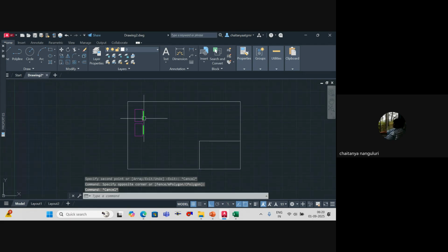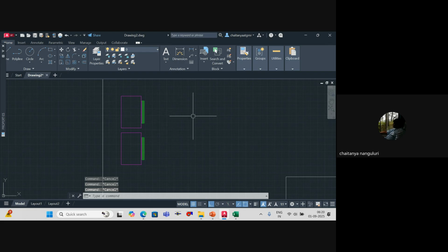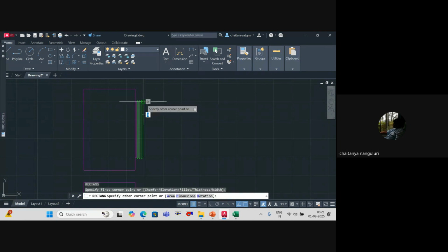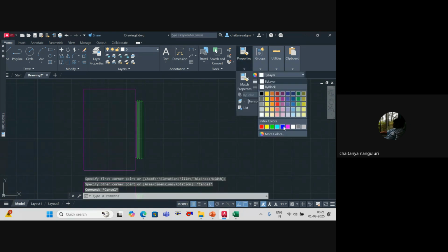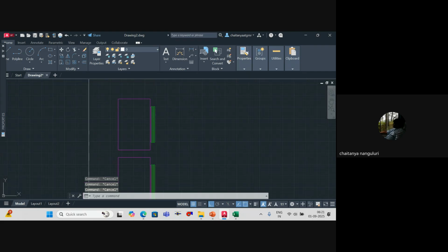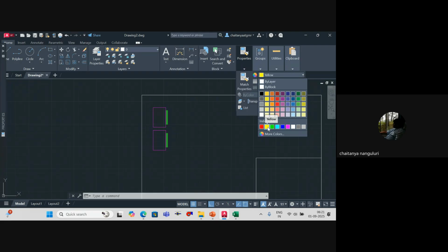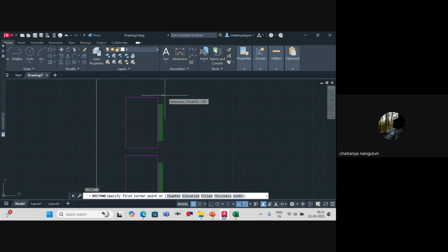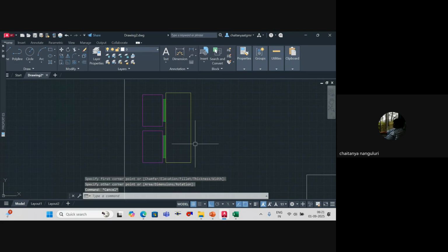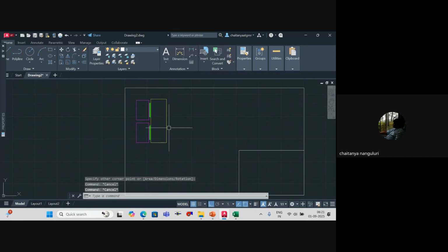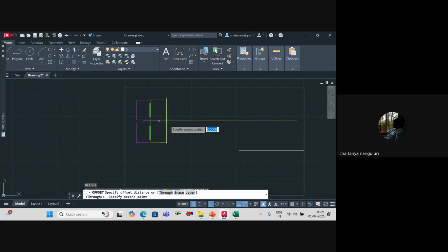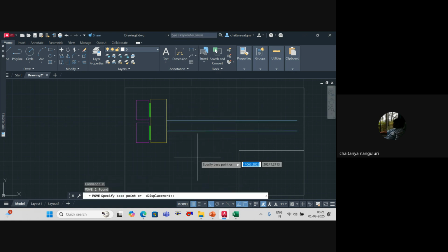Now, don't you think I should have some kind of common plenum so that when the air is flowing through, I'll have a plenum to connect and then have a common ducting? So let's say I've got a plenum connection. I'll draw it in another color, yellow, since this is not visible. So we have a common plenum here. This boxing, we call it a plenum, which collects from both the equipments. And then we use one duct to get connected like this. Yes or no?